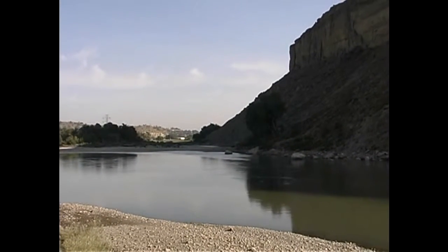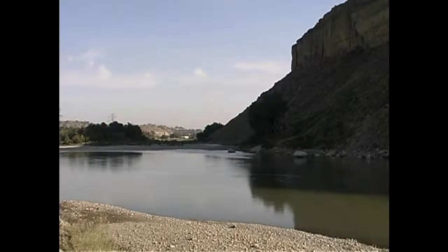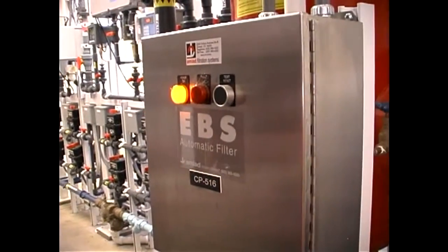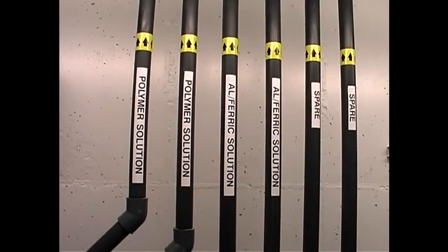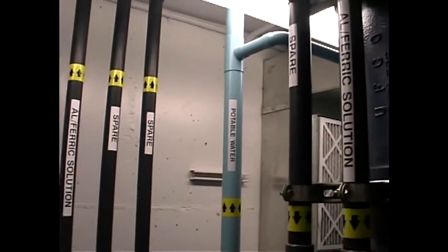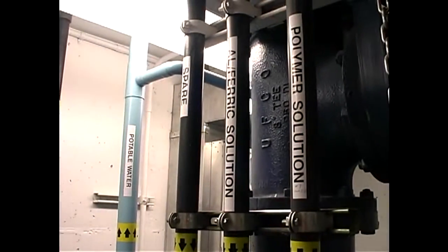Our treatment system here is a full conventional plant. We coagulate, flocculate, sedimentation, and then through filtration. We use a polyaluminum hydroxychloride, PACL, which is an alum blend, a proprietary alum blend. Prior to that, we used ferric chloride. Prior to that, we used alum. We went to ferric chloride because of our arsenic problems, when arsenic became an issue in the early 90s.